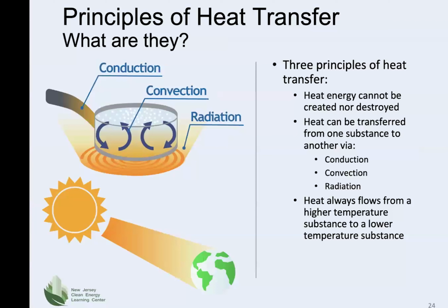Natural convection can be thought of as heat moving within a fluid that moves because of differences in specific gravity or differences in pressure of the fluid's molecules. The simplest example of this is hot air rises. As a portion of the room's air is warmed, the distance between those molecules increases, making that air less dense and allowing it to be buoyed upward.